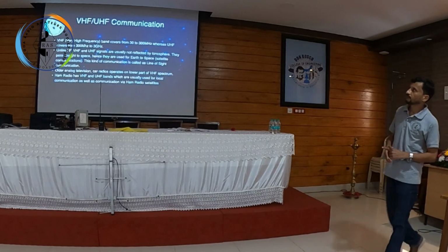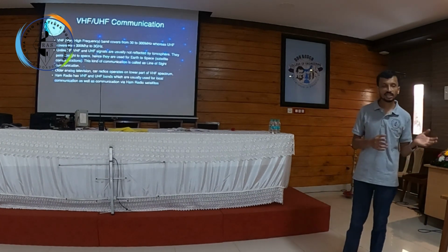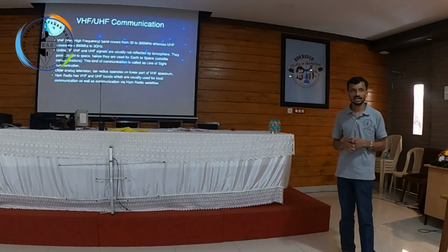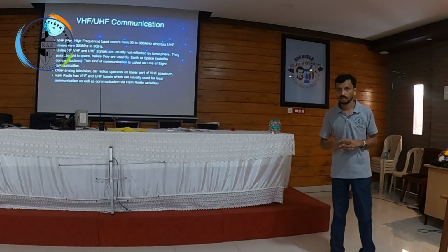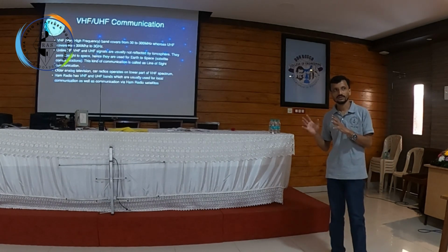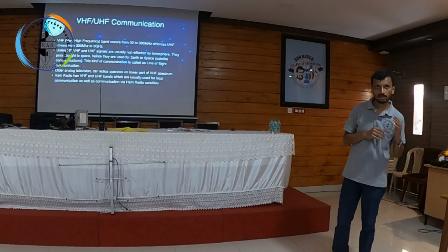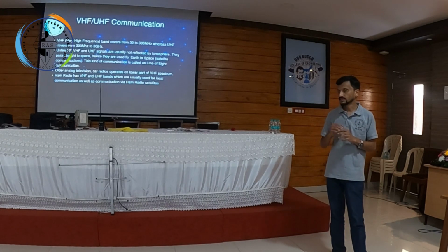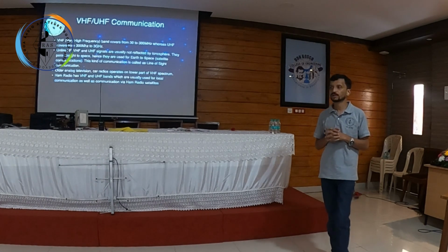Now HF stands for high frequency, which is from 3 to 30 megahertz. VHF is very high frequency, between 30 to 300 megahertz, and UHF is from 300 megahertz to 3 gigahertz. Now the thing is, VHF and UHF are generally not reflected by the ionosphere. They get passed through the ionosphere. Hence you cannot use this mode of propagation for communication. So this gets limited to only line of sight communication.